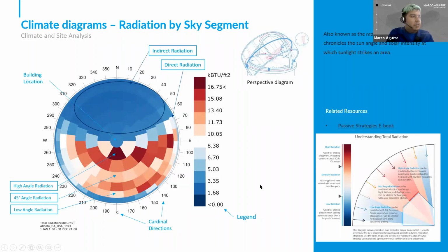When you have a lot of the radiation coming from the middle ranges, so if you just look out 45 degrees from a window, you have a lot of intense sun coming in that direction on a daily basis, things like light shelves, overhangs, fins, and shadow boxes can be great daylight control strategies. And when the radiation is coming directly above, and that's the most intense radiation, things like overhangs and cantilevers can be beneficial, and also smarter skylighting strategies. So instead of just using direct glazing above the building, taking advantage of things like clerestories or bouncing light into the space.